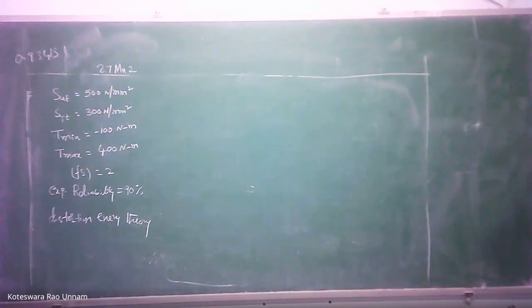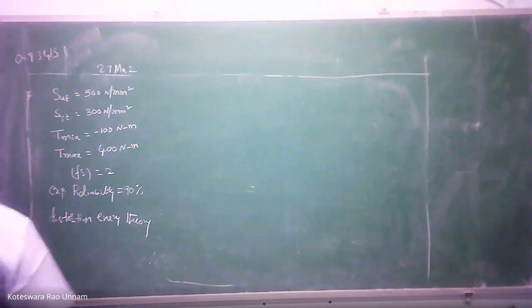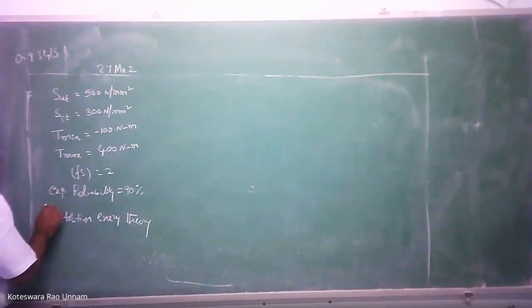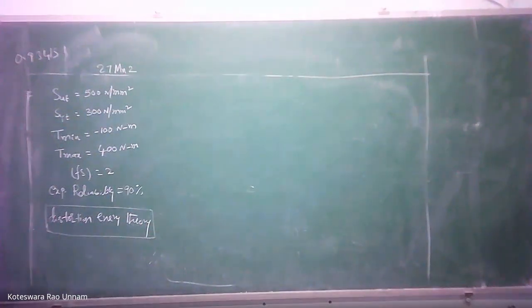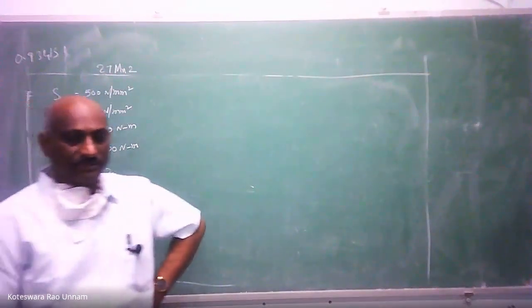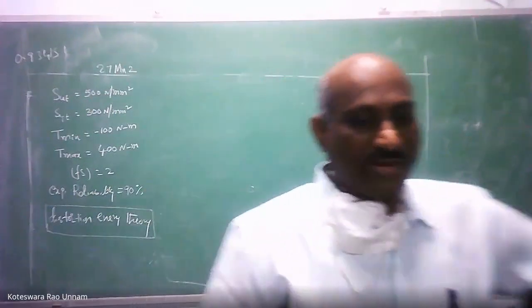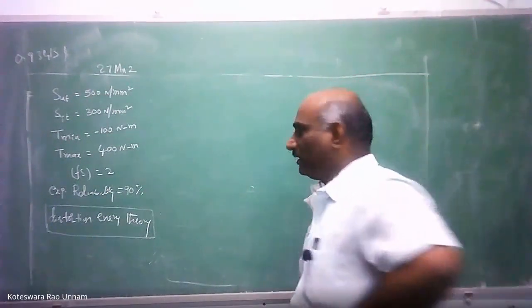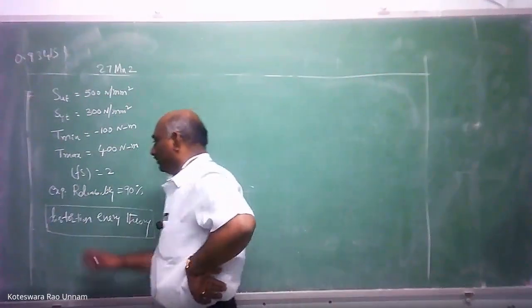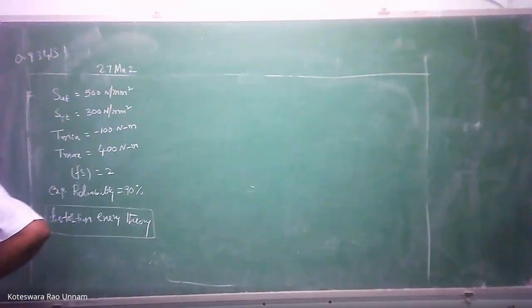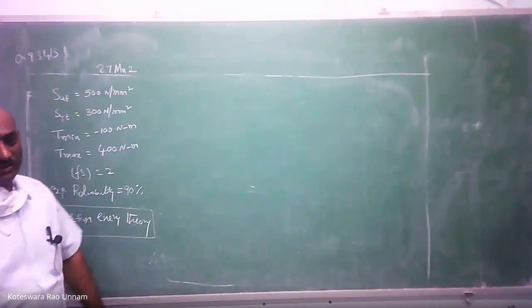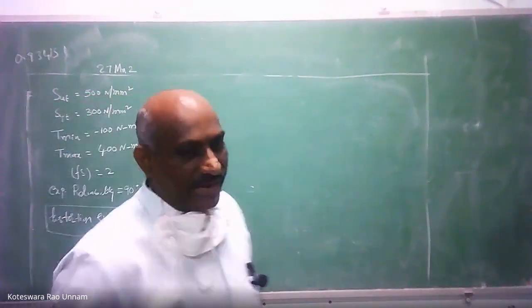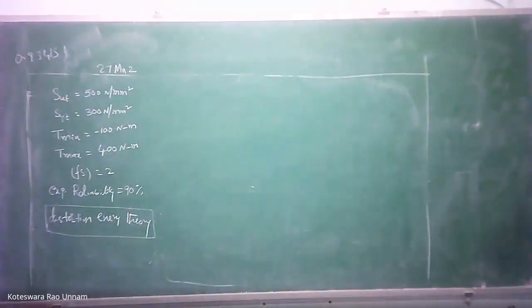So in this, one important thing you can consider is that you have been given an additional statement in the problem. So far in all our stress problems, we haven't talked about the static failure theories. We haven't used any static failure theories, but in this case, he has specially mentioned to assume distortion energy theory of failure. So, do you have any idea why he has given this option?